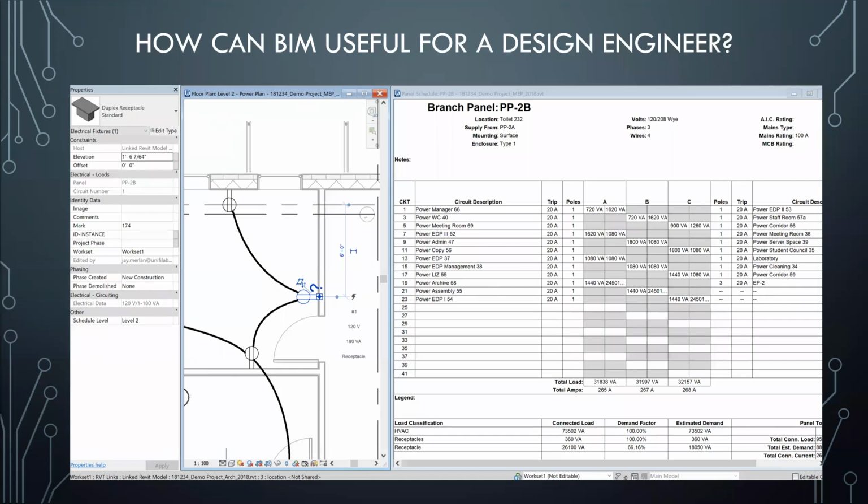So our first example here is really for our electrical engineers on the line. Earlier in the presentation, I mentioned that before BIM, we used pencil and paper and eventually moved to CAD. Well, even in the early CAD days, you'd most likely need to count system components manually. And I personally remember having to highlight symbols on printed floor plans to count fire alarm devices on a circuit for calculating voltage drop for that circuit. And not only was that excruciatingly tedious, but there was also a lot of risk associated with that process, because obviously the possibility of human error is always a factor.